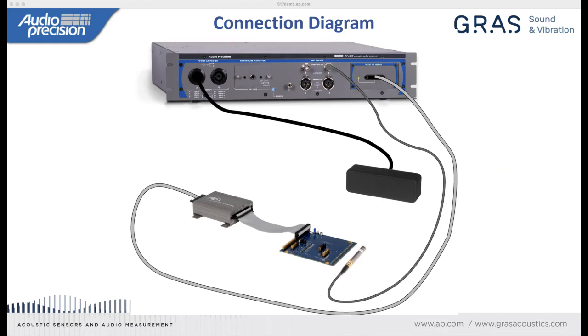And in fact, the more challenging things will get, because in today's demonstration, I have the reference microphone very close, within a few millimeters of the lead microphone under test. If I really cared very precisely about the response all the way to 20 kilohertz, that would present a challenge, because to get the microphone close enough, it would then be interfering with the sound field.